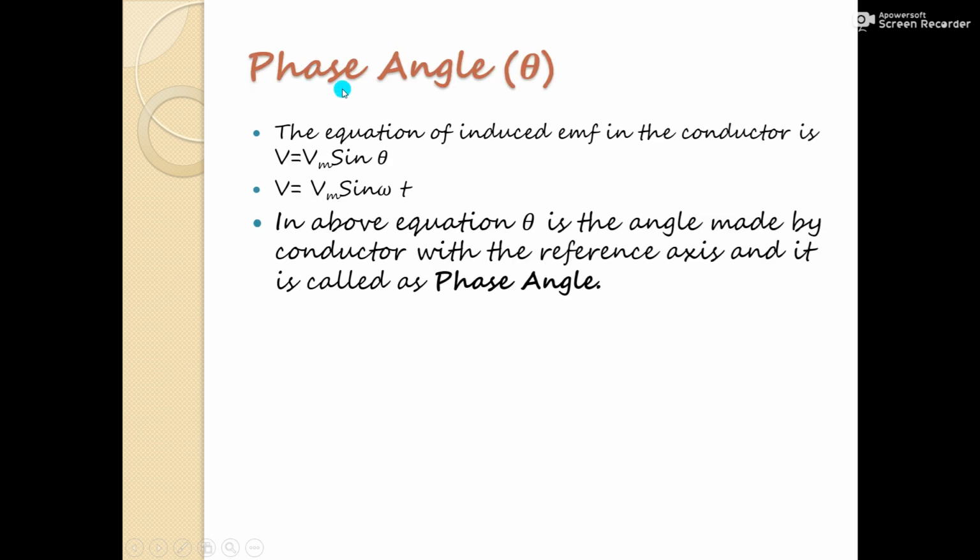Let us have a look at the phase angle, which is represented by theta. The equation of induced EMF in the conductor is given by V equal to Vm sin theta. We can further write it as V equal to Vm sin omega t. In the above equation, theta is called the phase angle, which is the angle made by the conductor with the reference axis.